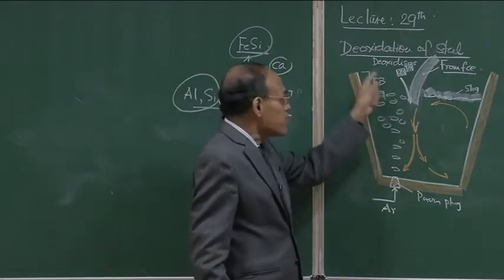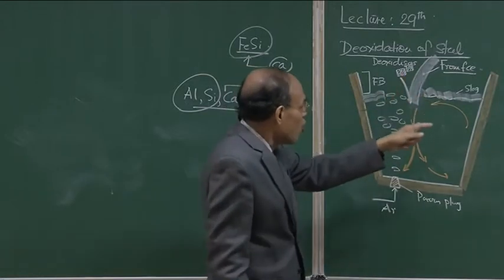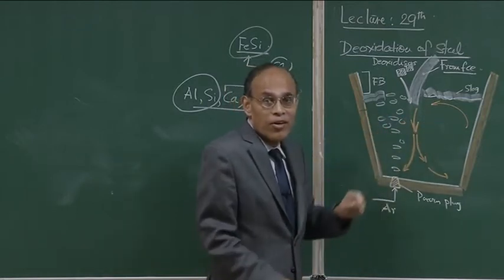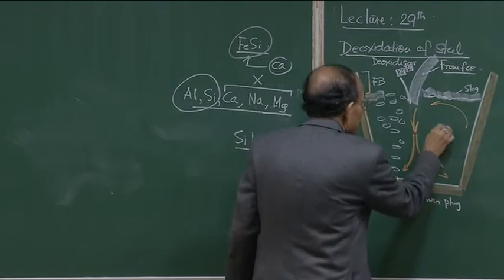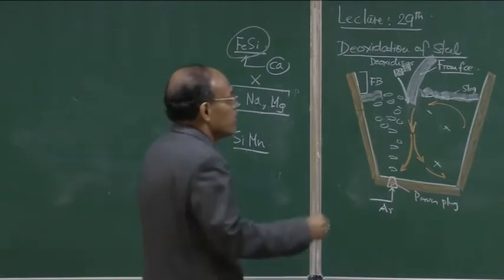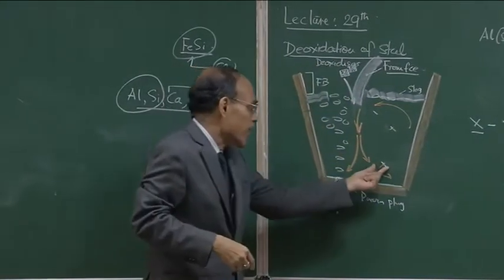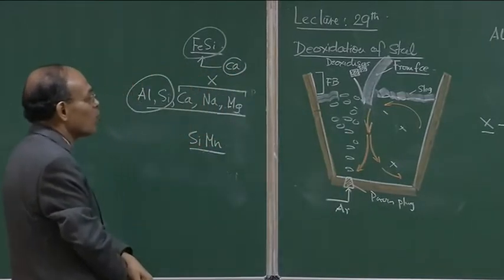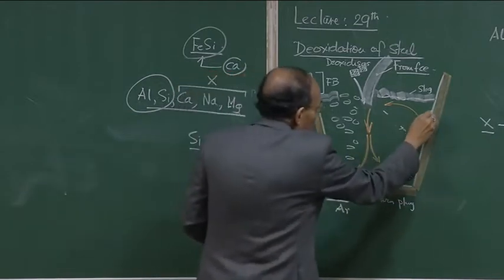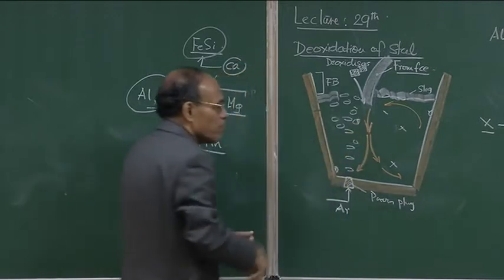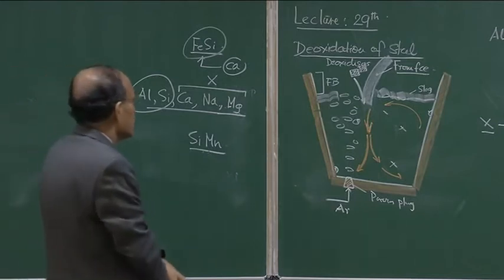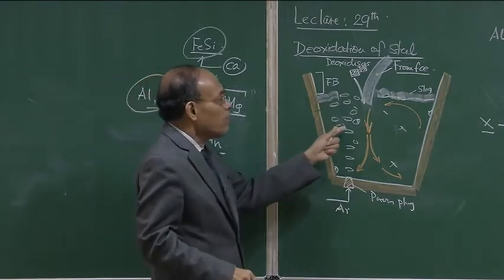Now, when you add deoxidizer elements, these deoxidizer elements melt and then dissolve, and therefore the reaction can take place anywhere here. Okay. So the deoxidation product can be generated anywhere in the system because of the circulatory nature of molten steel containing dissolved aluminum and dissolved oxygen reacting. Nucleation and growth can take place on this wall. It is a heterogeneous reaction, here also, on the bubble surface also, everywhere multiple sites are possible for nucleation of these new products. The solid products, okay, are basically oxides.